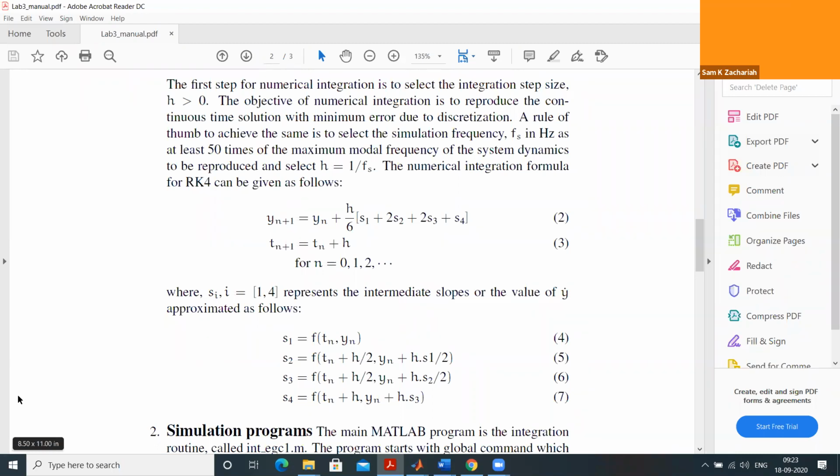There the criterion is that the sample and hold (S/H) process should not introduce unnecessary lag. Suppose the phase margin is 45 degrees in the closed loop control system. The additional phase lag due to sampling and holding should not exceed some 2 to 3 degrees. That is the criterion.